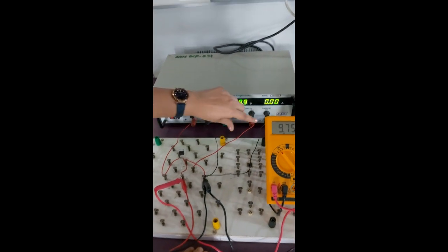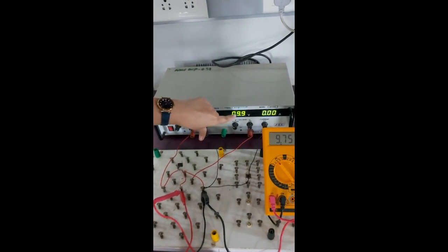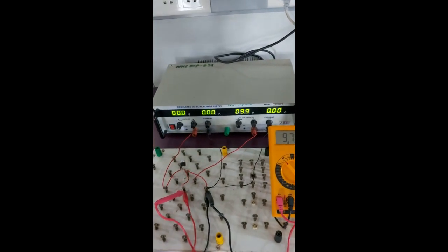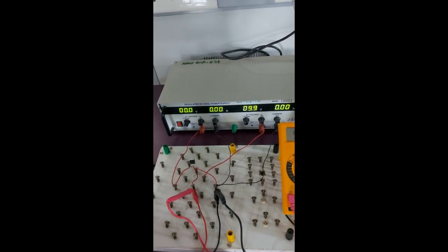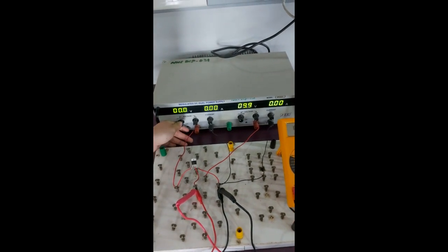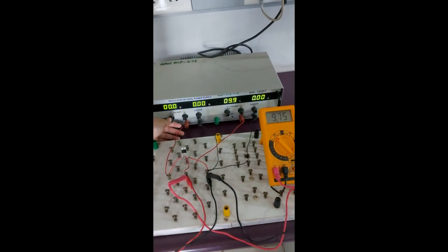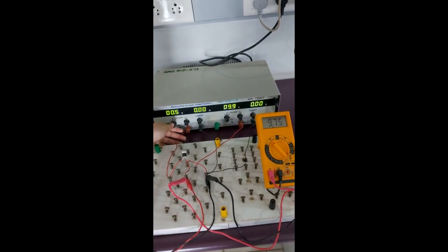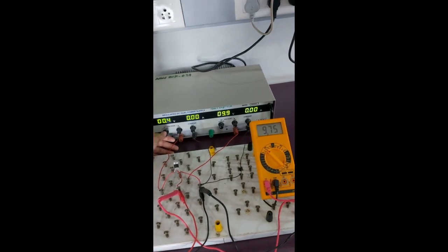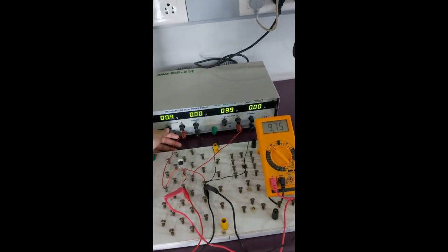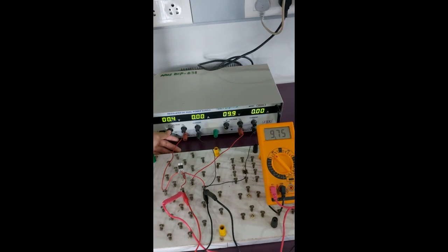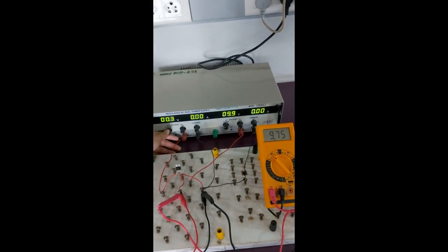You can see here the fixed power supply of around 9.9 volts, the supply voltage connected between the drain and the source terminals, and this is your drain resistance, RD. So now I am going to slowly vary the gate to source voltage and observe the drop across the drain and source terminals. It's at 0.0, so I will slowly increase, and you can see the drop across the drain to source terminals is 9.75. We have given a supply of 9.9 with a slight drop across the drain resistance. The value coming is 9.75.